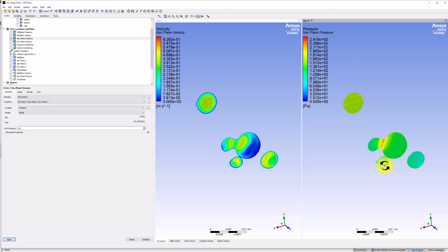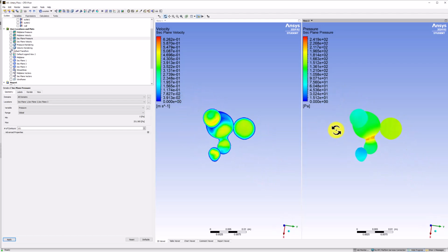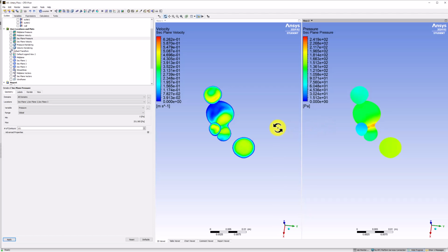Near the outlets, we can see that the velocity profiles have recovered to a distribution that is more similar to the inlet. The pressure, again, is approximately constant across the plane. Looking at the pressures together, we can see that the pressure remains approximately constant along each profile, but decreases as the flow moves towards the outlet.